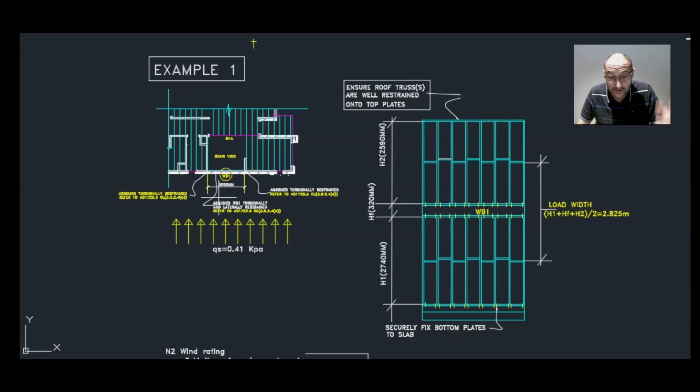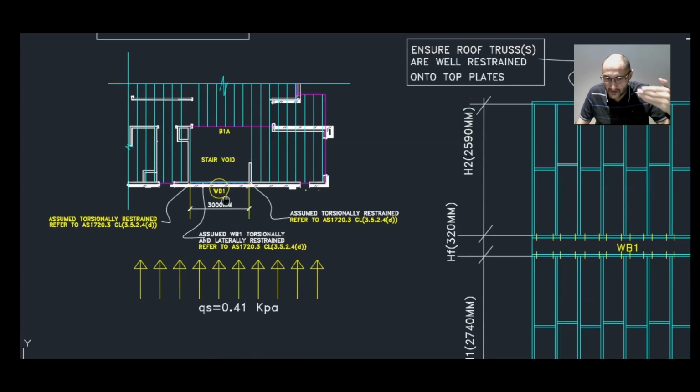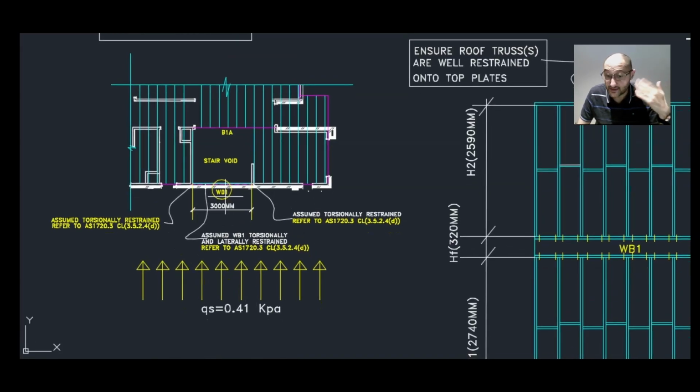WB1 is given to us as 2 beams laminated together. For wind beams, generally speaking, it is probably a better design option to use a single thicker beam rather than laminated beams, especially nail laminated, and I think the code kind of discourages nail laminated. Anyhow, for the sake of this example, we will use screws as our fixing choice for laminating these beams.